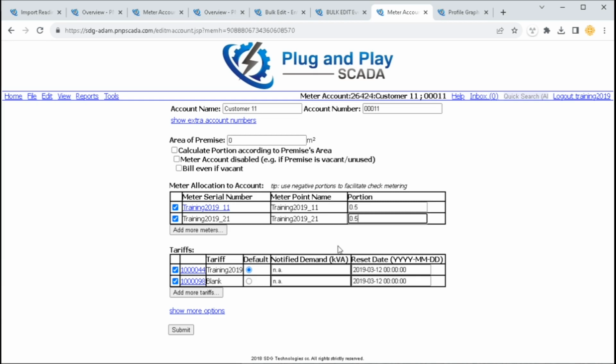So, for example, if a shop is split into 2, and each tenant agrees to pay half of the electricity bill. You can also add some meters and subtract others. So you can, for example, add the incomer meter and subtract tenant meters. What is then left is losses and common area.